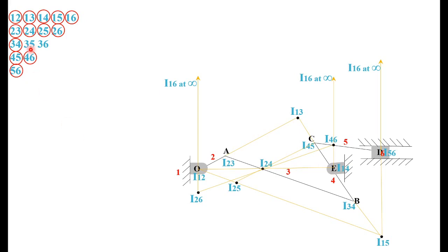Then next we have two remaining, 3 5 and 3 6. Now you see how you will locate 3 5. To locate 3 5, again you have to take a combination. First you try with 1. So taking 1, the combination will be 1 3 5. In case of 1 3 5, the centers are 1 3, 1 5 and 3 5. So we have 1 3 located, 1 5 also located. Then you can use that combination to locate 3 5. So note it down, 1 3 5.